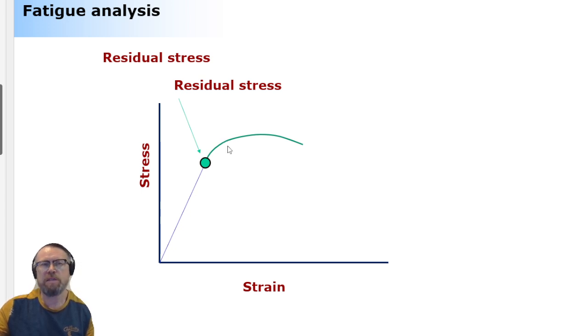That's bad because now any kind of extra strain, any kind of extra loading will make the structure deform plastically. Now keep in mind, very, very locally, there's going to be local plastic deformation, and this local plastic deformation is exactly where the crack is growing. This is a mechanism that makes welded structures very vulnerable to fatigue damage. Okay, now you say, yeah, all right, so let's change the material to be high strength steel.